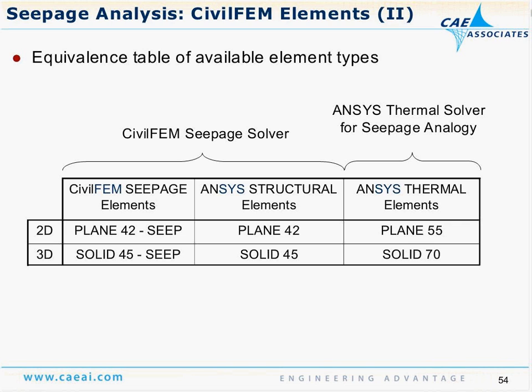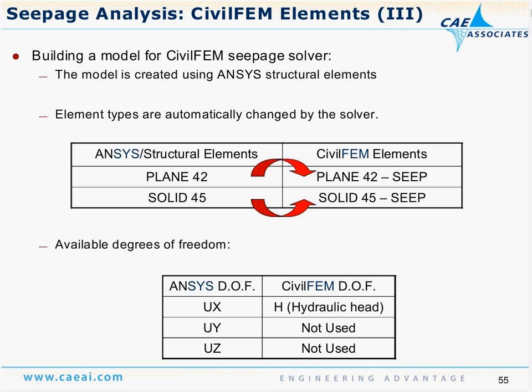Internally, the CivilFEM add-on subroutines give you the ability to calculate the hydraulic head, where it makes an analogy and takes the UX displacement degree of freedom and uses that as the degree of freedom used for the hydraulic head to calculate the seepage.